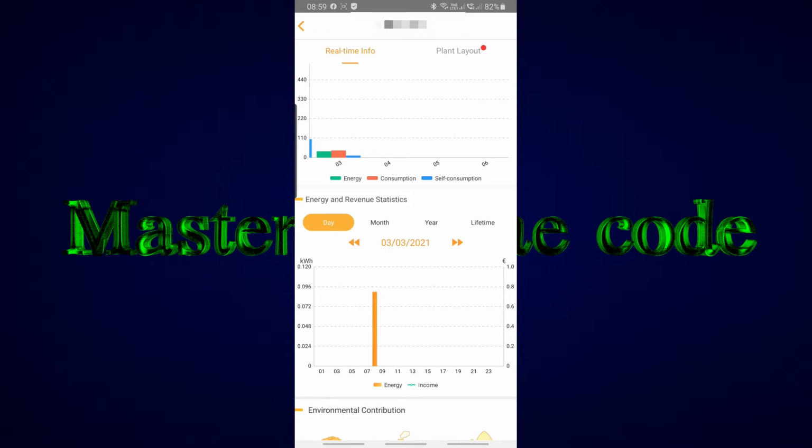It's some downside of that application from Huawei, because in different countries, different energy suppliers have different terms. So for example, here in Poland, when you have an installation that is less than 10 kilowatts, so that is also why I have that 9.9 kilowatts installation, when you export energy to the grid, you can only get 80% of that energy back for free. And if you have a more powerful installation, more than 10 kilowatts, you can only get 70%. So it's the difference, and it works differently for different countries.